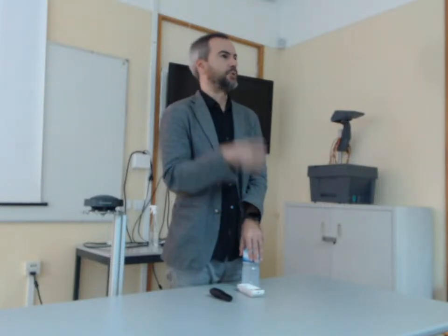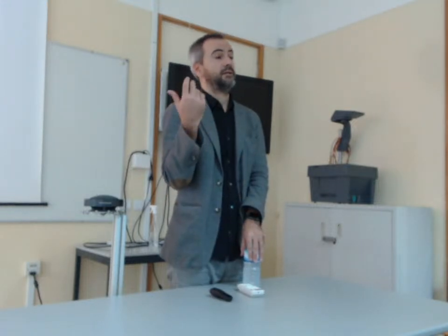The question is only between the two structures. Yeah, but we don't have earthquake. If we had, this was not possible. We should think of some bracings or other system to provide lateral stability to the structure. But we didn't have wind because it's inside the building, and in Madrid we don't have to consider seismic analysis. No, thank you. Okay.